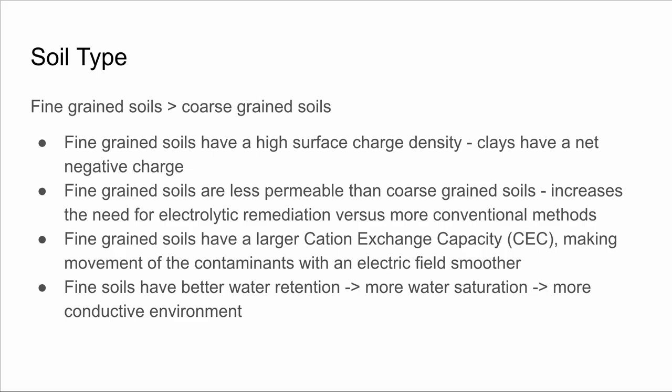Fine-grained soils also have a larger cation exchange capacity, and all that means is it makes the movement of the contaminants with the electric field smoother. The contaminants will move faster within the porous medium. They'll move in a more predictable pattern.